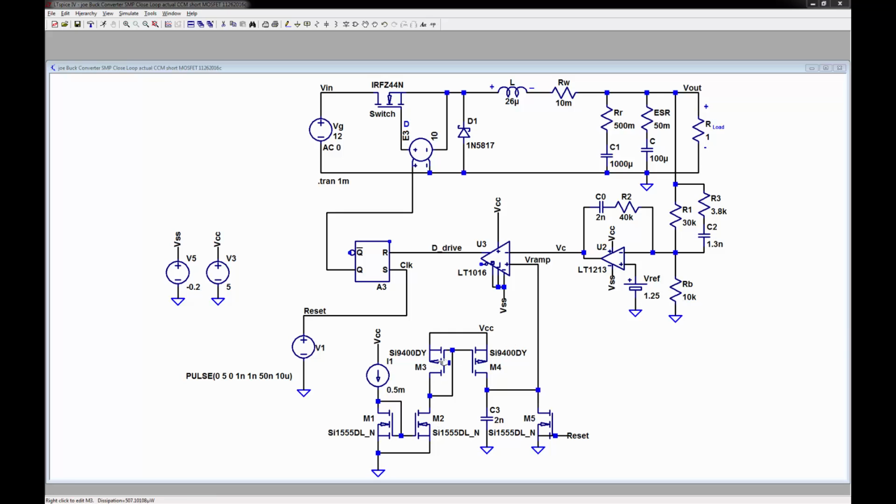These are PMOS. So how do you build another mirror? The same way you did this one. Now, the current here replaces a current here. It looks like a current source going down. Well, again, there's no current here. Therefore, that current comes here through here. That current will equal this current, which will be the same as that current.